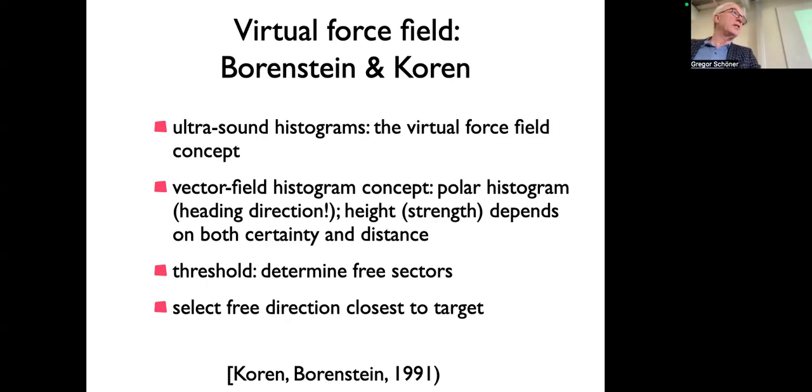This is essentially a distance sensor, and the ultrasound distance sensor is nice because it has time of flight measurement of distance with the speed of sound, and therefore it's an exact distance measure with some precision, but it's not in principle exact. Compared to the kind of stuff I was showing, where you look at the reflected light, which is just heuristically some distance dependent, but it depends on the reflective properties and all kinds of things.